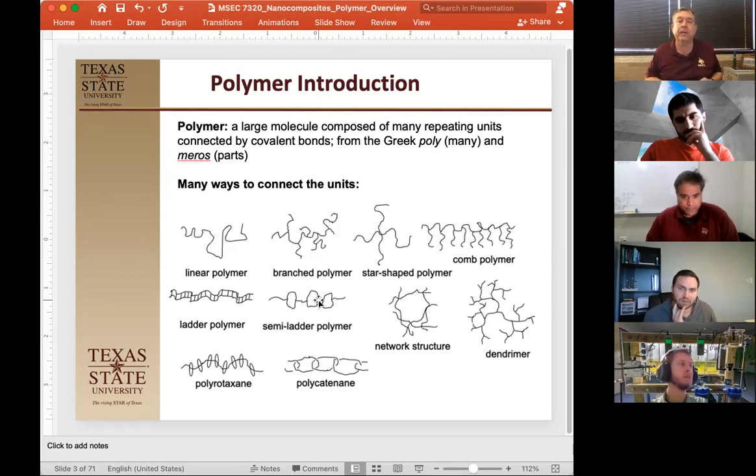Most polymers are what we consider linear polymers, where they just grow from head to tail, all the way along. However, there are many different systems like polyethylene, or you can incorporate a trifunctional material, which will allow you to have a branched polymer. And branched polymers have different properties than linear polymers. The more linear the polymer is, it might have different properties like stronger or higher crystallinity.